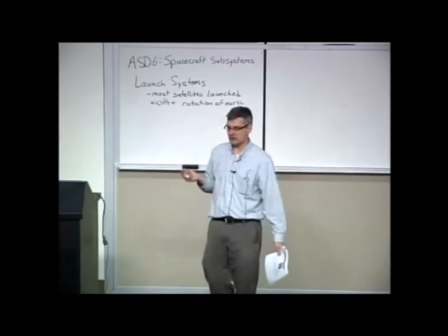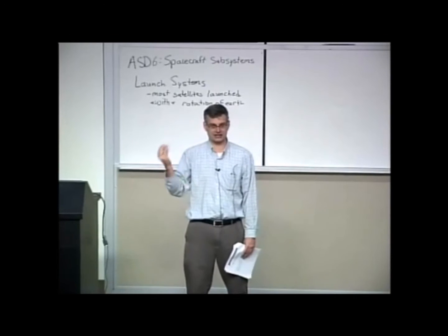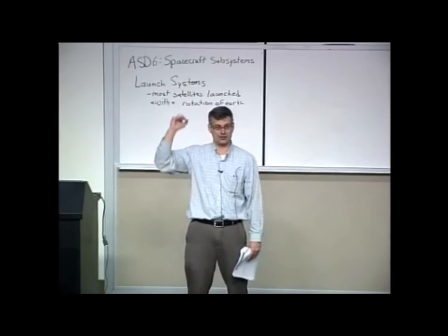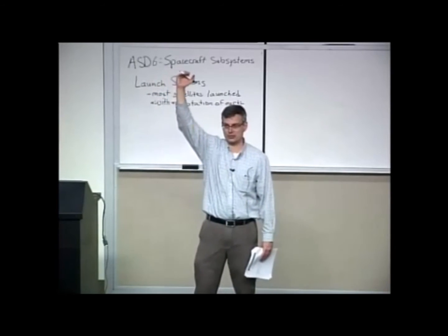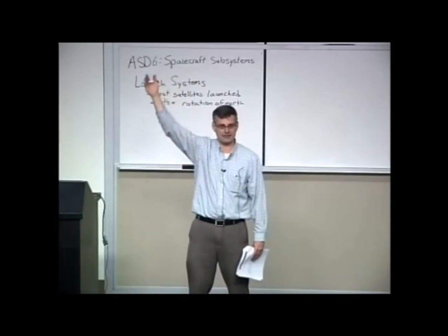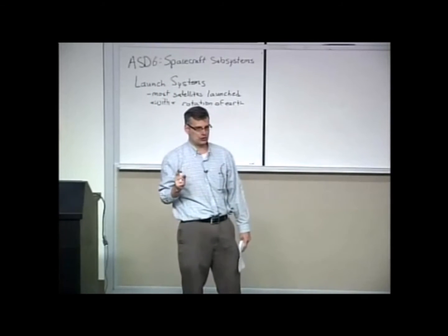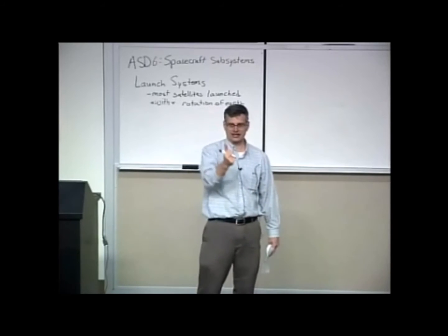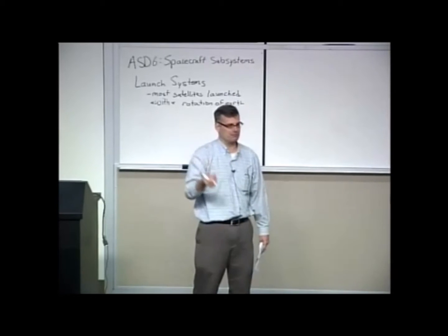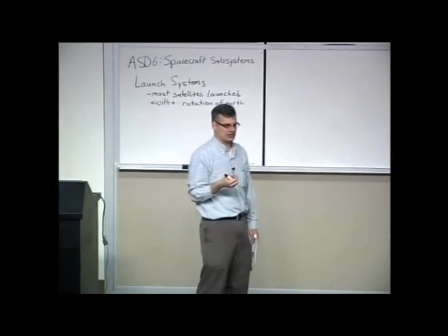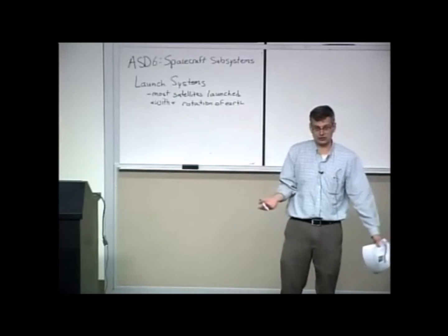And we're starting off with just a few hundred meters per second with the rotation of the Earth. So we have to add a lot of kinetic energy, and we have to overcome 1,000 kilometers of gravitational potential energy on top of that. And so every little bit helps. The fact that you launch with the rotation of the Earth instead of against it means that you don't have to overcome that initial few hundred meters per second that the rotation of the Earth imparts to you. That's a substantial rocket fuel savings, actually, and it reduces the cost.